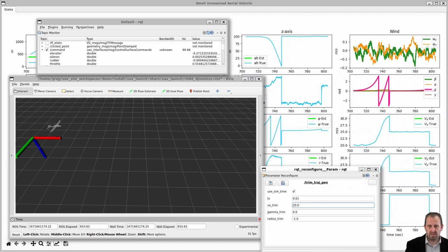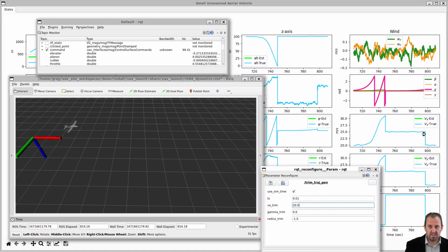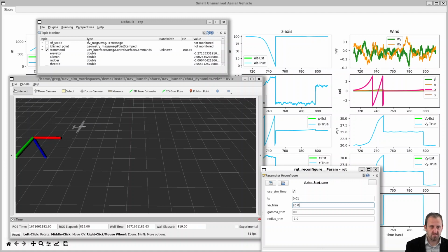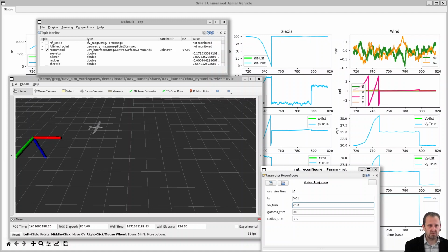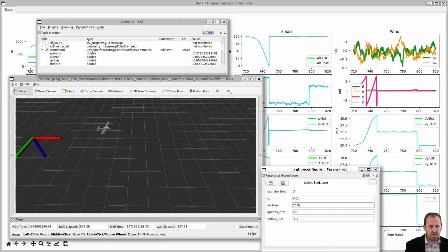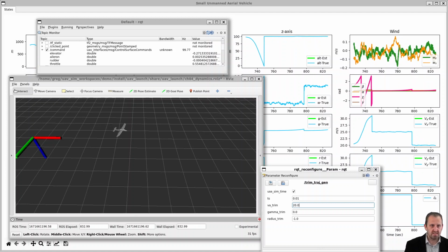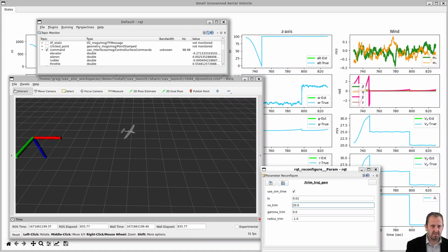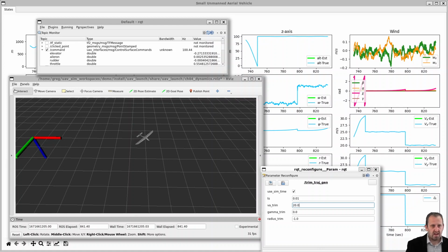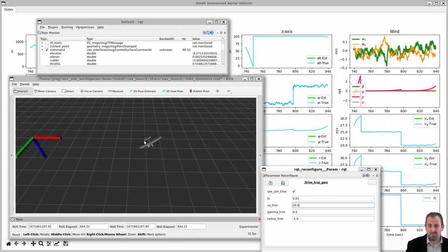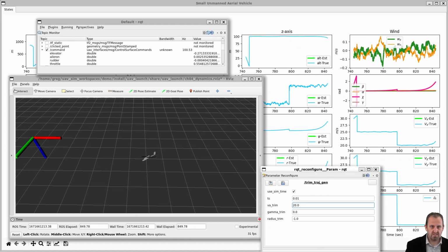And you can also see over here that our actual airspeed velocity dropped from 25 down to 20. But the main idea here is when we develop the trim trajectories, we're developing these so that we can linearize about that trajectory and design control laws to keep us on the trajectory. You can see here that because of that pitch angle, we were operating in a condition where these nonlinear effects caused us to, now the aircraft is definitely not flying straight, right? But it did for several hundred meters. So it was able to fly straight for quite a while.